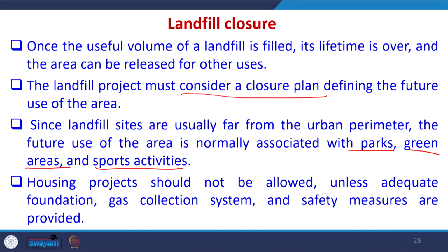So, these are the normal ways in which the landfill can be used after closure. Housing projects should never be allowed on the landfill unless adequate foundations, gas collection system and safety measures are provided. Generally, housing projects should never be allowed on a closed landfill.